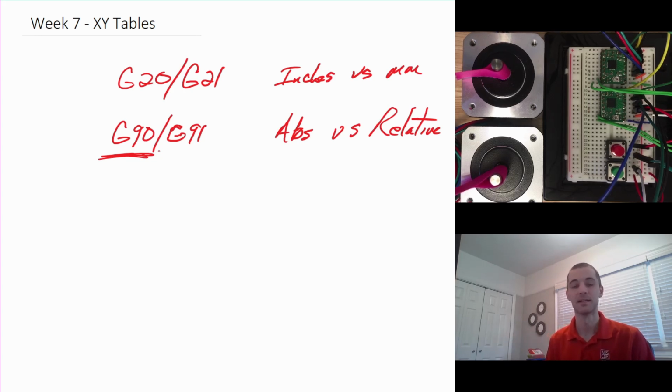And that's why I like the G80 series, where you end up using it in the CNC machine class that I teach pretty frequently on projects. Because again, you don't want to have to code 20 lines of G code every time you want to drill and tap, or drill and ream and then hone a particular circular or cylindrical feature on your part. You would prefer to just write one line of code.